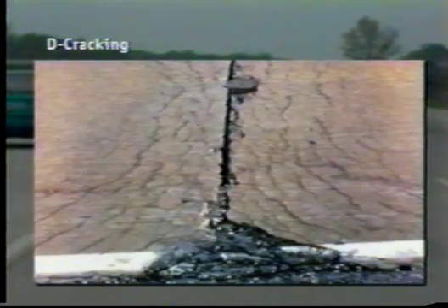The D in D cracking stands for durability cracking. This is recognized by closely spaced, crescent-shaped, hairline cracks occurring adjacent to joints, cracks, or free areas, initiating in slab corners. You can also see a dark coloring of the cracking pattern in surrounding area. Poor quality aggregate absorbs moisture, causing the aggregate to break apart during freeze-thaw cycles. This generally only occurs where moisture is present at joints. For a temporary repair, a partial depth asphalt patch similar to pothole repair can be used. For a permanent cure, a full depth repair is required.